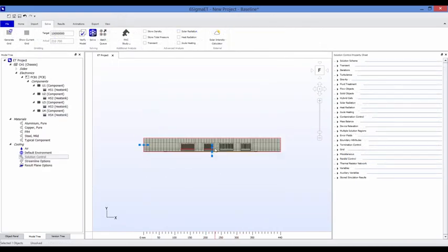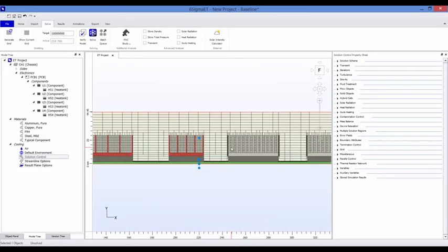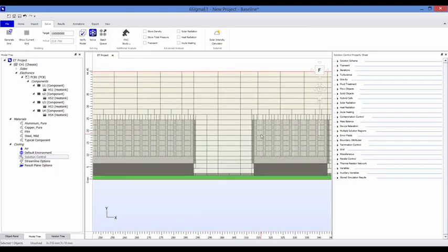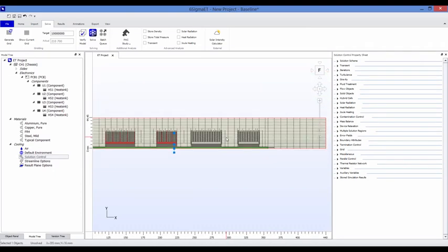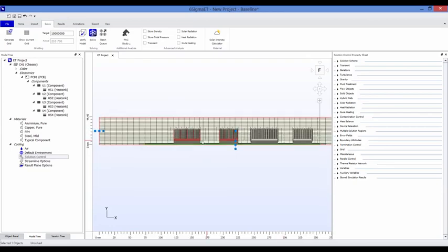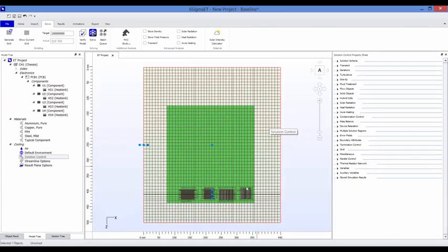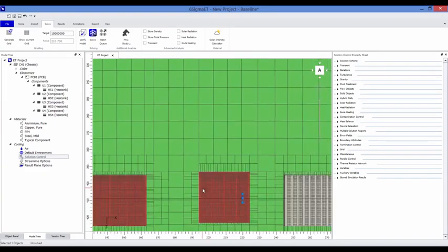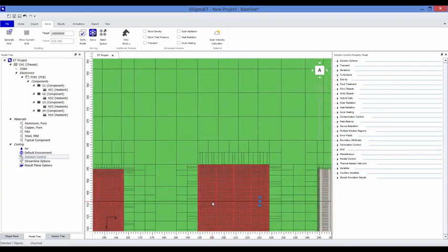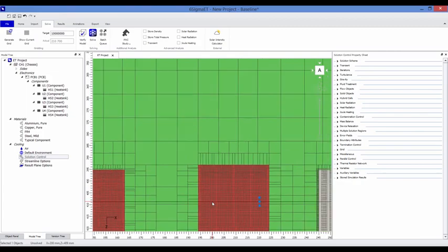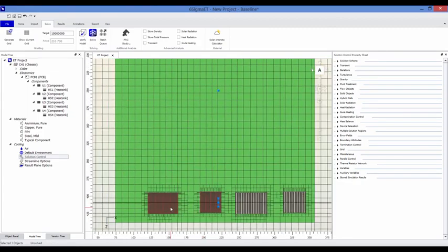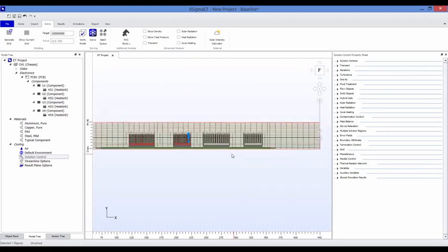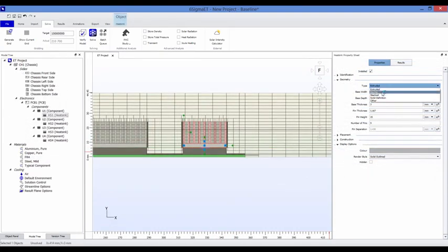As you can see, the automatic grid generated accounts for the boundaries on either side of the heat sinks with just enough grid between the plate fins to capture the jet and at least one cell to account for the thickness of the fin. From the top, you can see that the grid captures even the tricky staggered arrangement quite effectively. This automated process, developed through years of experience and research, enables any user to achieve accurate results with minimal effort. Let's see how ET handles the grid for imported geometries.